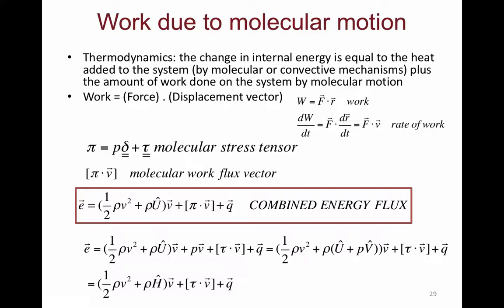And heat is transferred, but H is of course something that we have to have. It's typically tabulated or given by experiments. Okay? So this is called the heat transfer coefficient.